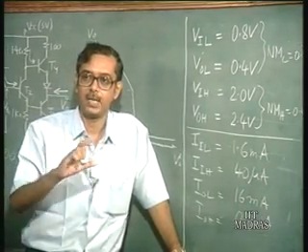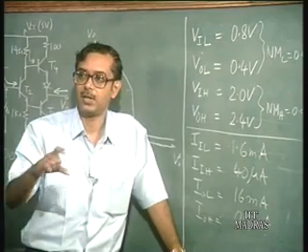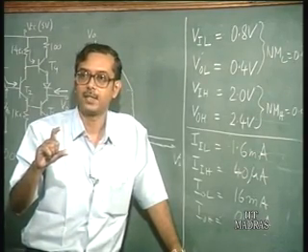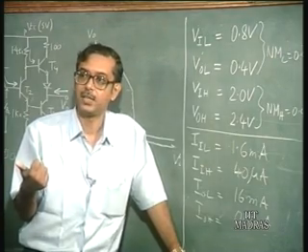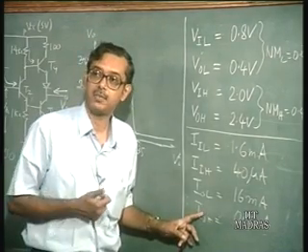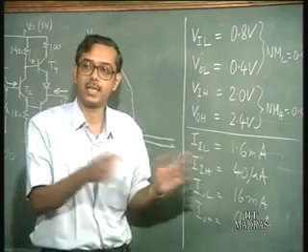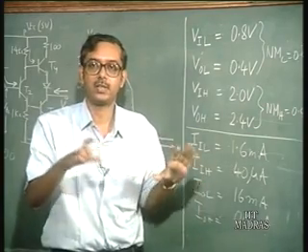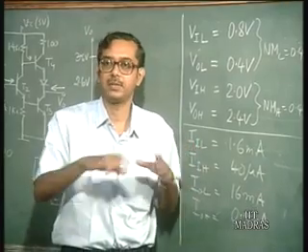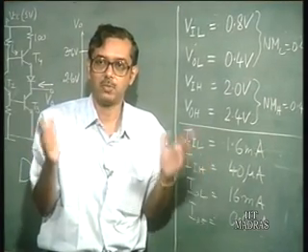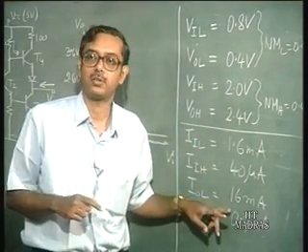You must be very careful whether a CMOS gate can drive a TTL gate. You have to look at these current specifications; you cannot just connect them because they are NAND gates and assume it will work, because it does not. You must be very careful of the fan out criteria.